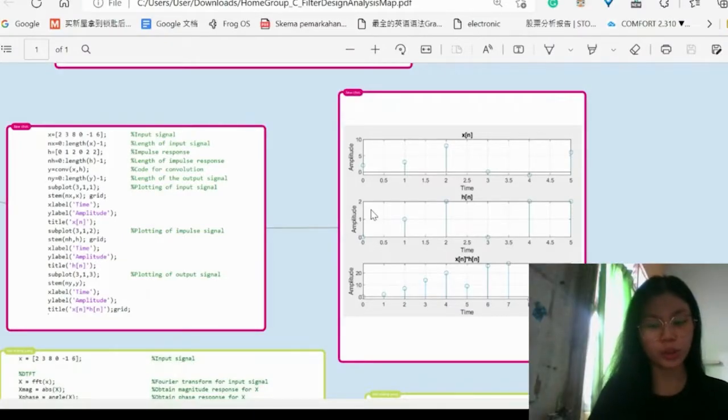Hi, my name is Lina Tri. So today I will explain how to use the convolutions to filter the noise. Convolutions is using two inputs to filter one through the other, and the convolutions of one function, which is input signal, with second function, which is impulse response signal, will give the output of a linear time invariant system.